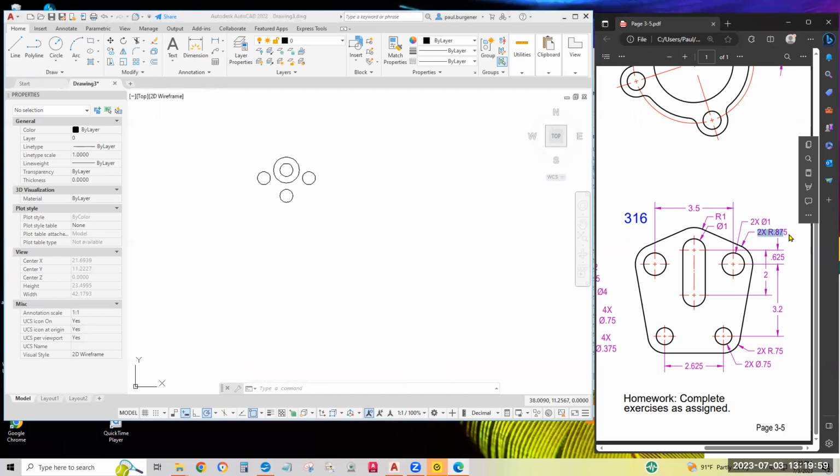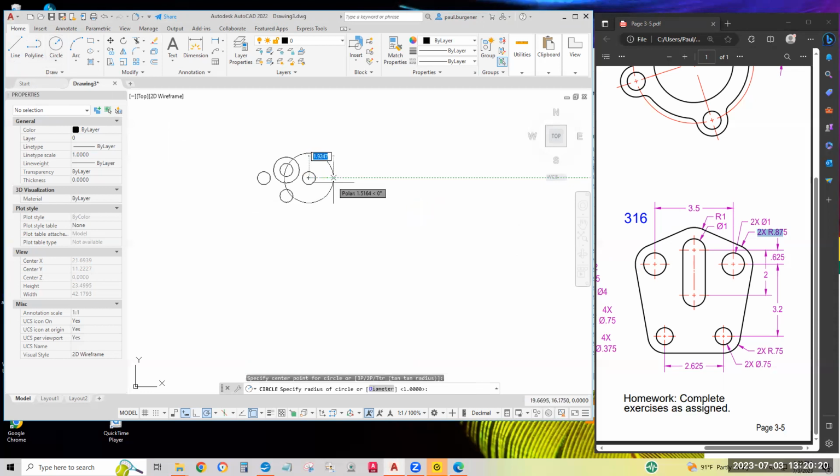And this arc can begin by a 7/8 radius circle. I should have waited for it to be made before I mirrored across, always something. All right, we'll click circle center radius, snap, and 7/8 for demonstration's sake. So let me demonstrate. 7/8, enter, works the same as typing 0.875. Okay.